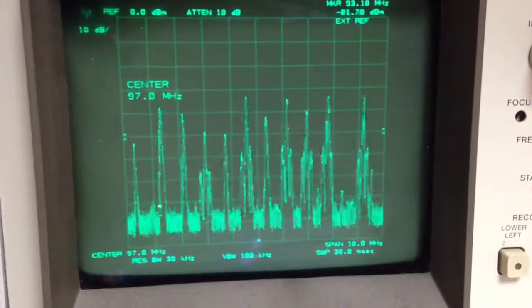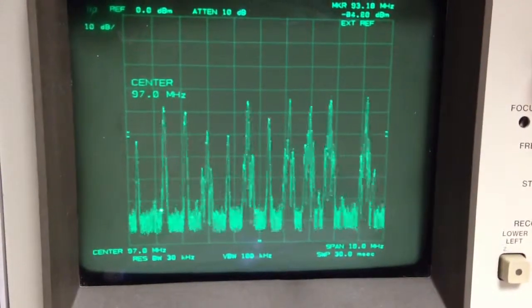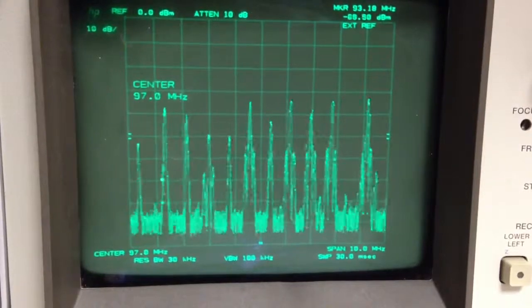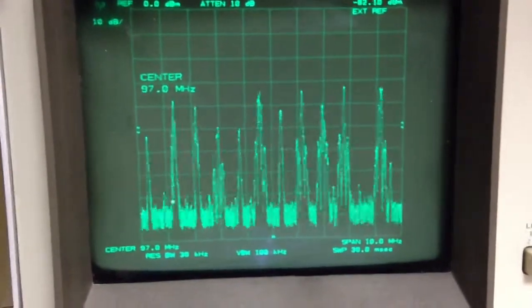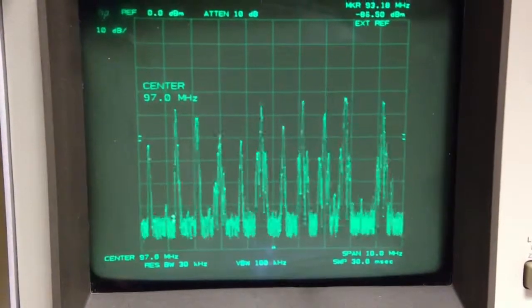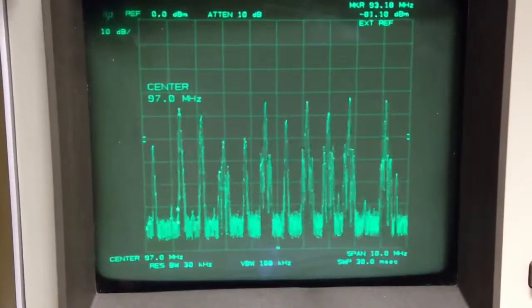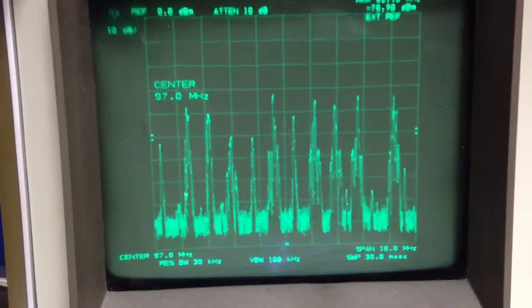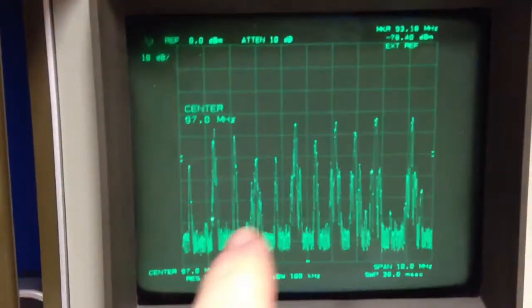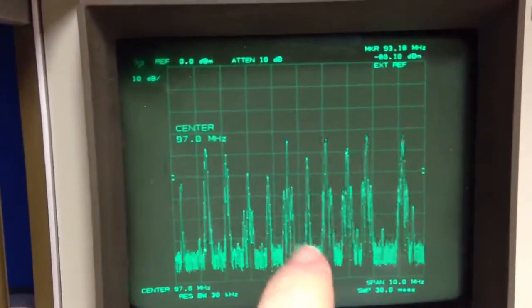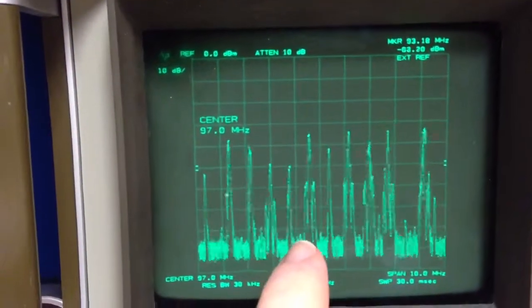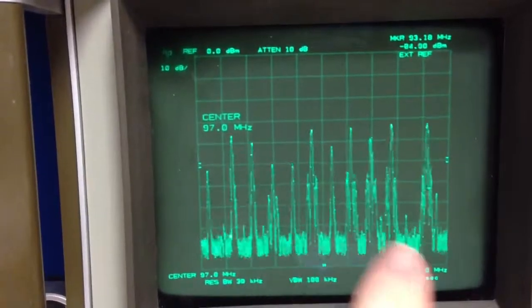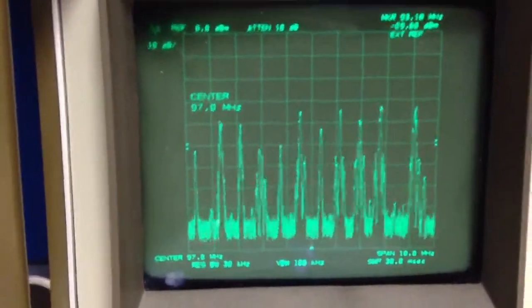Yeah, this is a demonstration of using GNU Radio and a USRP SDR to transmit audio in the FM whitespace. What we see here on the spectrum analyzer, it's tuned to 97 megahertz center frequency and 10 megahertz bandwidth, so you can see all the commercial FM broadcast in the area. So what we want to do is transmit our own wideband FM audio between all these channels and utilize the whitespace. So we come up here to our GNU Radio block diagram.